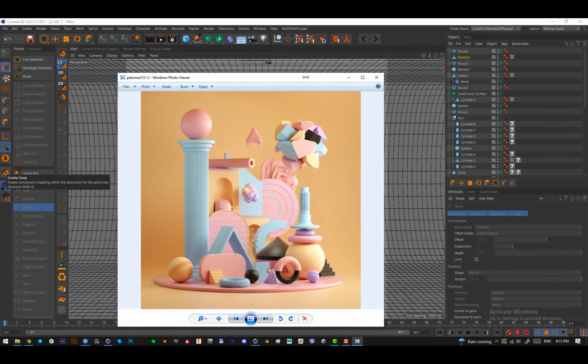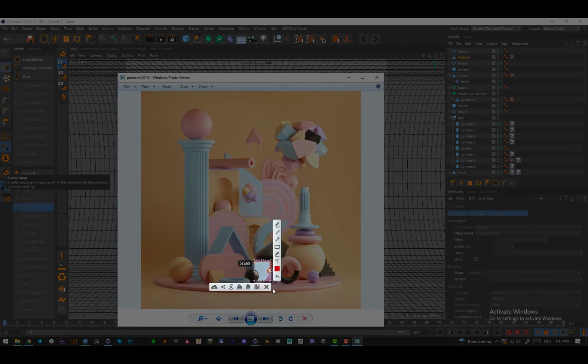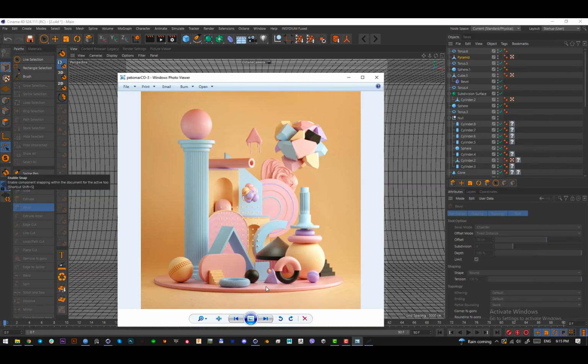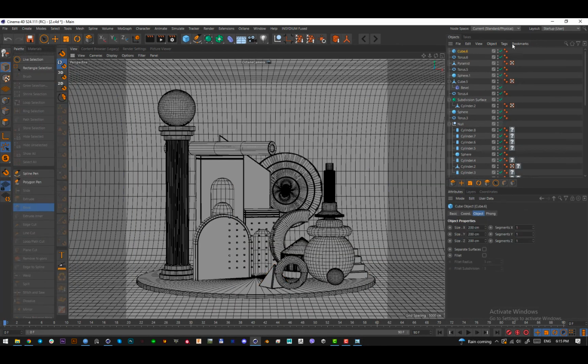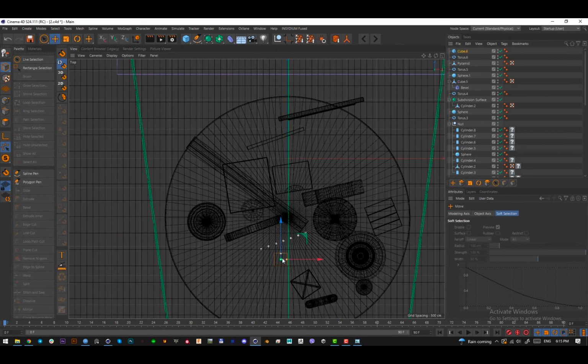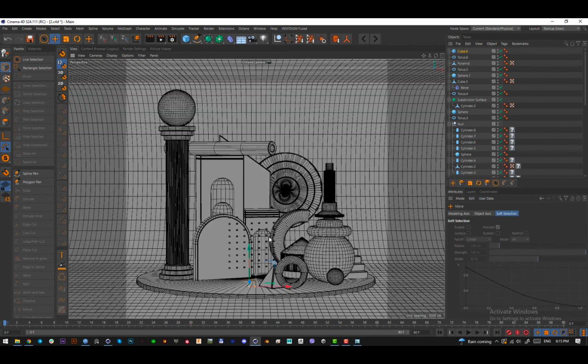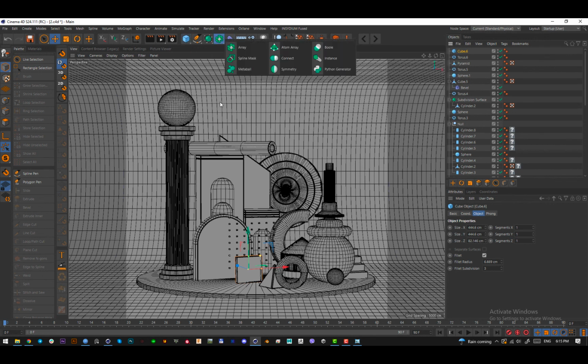Now behind the pyramid we have this shape. This is very simple, so let's do it. We want a cube, put the cube here, make it thin, pull it up, scale it up like this, put it here. Okay, add some segments, and now use the boolean, so add this cube as a child to the boolean.